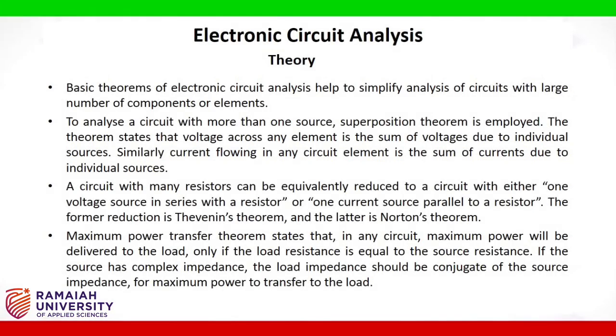Basic theorems of electronic circuit analysis help to simplify analysis of circuits with a larger number of components or elements. To analyze a circuit with more than one source, superposition theorem is employed. The theorem states that voltage across any element is the sum of voltages due to individual sources. Similarly, current flowing in any circuit element is the sum of currents due to individual sources.